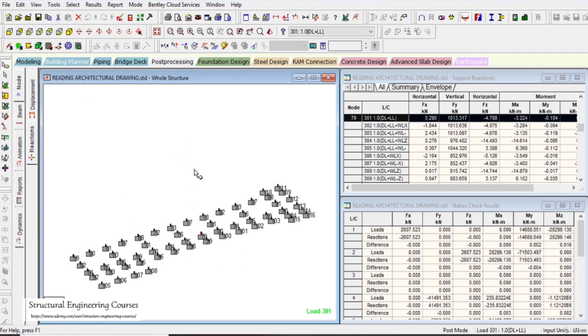Fy is the vertical force, and if Fy is positive, then it is a compressive force, whereas in some cases Fy is negative, and then basically the footing is completely in tension. This is also a mistake that most new engineers make. They simply ignore the negative sign and take the positive sign for the design. That can lead to catastrophe, as your footing can be in tension and the structure may simply overturn in that case.